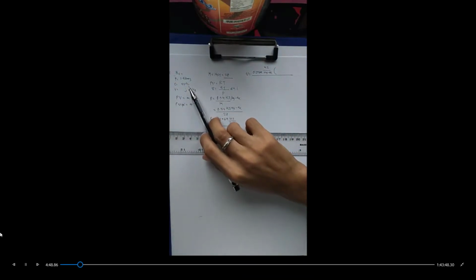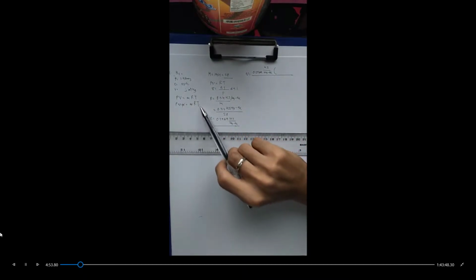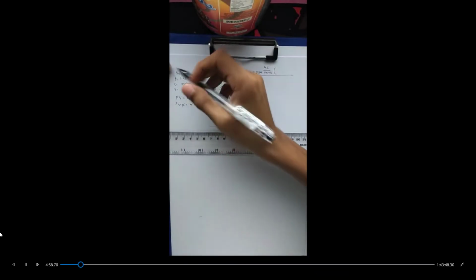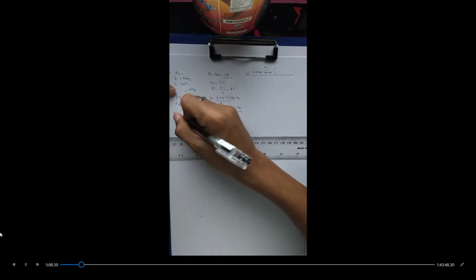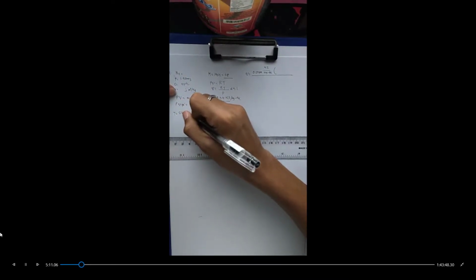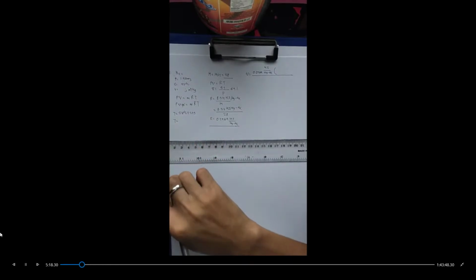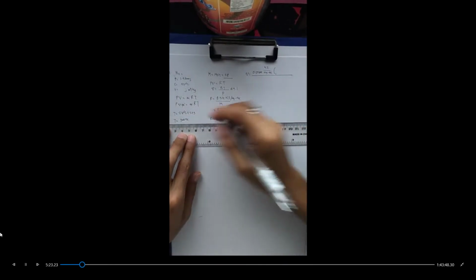Our temperature is in degrees Celsius, and in using the ideal gas equation, the temperature should always be in absolute. So we need to convert 27 degrees Celsius to absolute. In the metric system, the absolute temperature is in Kelvin. So we need to convert the temperature in Kelvin. The conversion is degrees Celsius plus 273. So our temperature now becomes 27 plus 273, 300 Kelvin. So this is our absolute temperature.